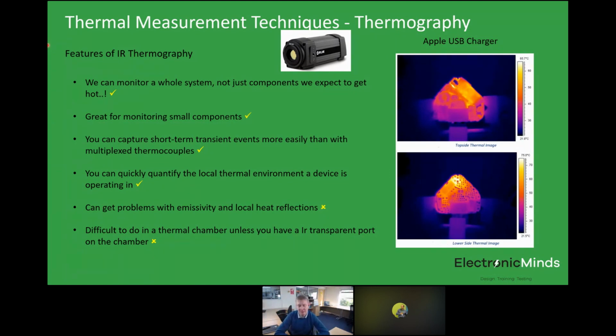On our earlier webinars talking about magnetics design, we talked about fringing effects. If you look at a standard E-core transformer and you put a gap just in the center leg, you get fringing fields going around that gap, and they can start to impinge on the first layer of primary winding and cause loss in that layer. There was a rule of thumb that I don't know how accurate it is, but it's been told to me a few times over the years: if you can keep your metalwork or your winding a distance of about 3 times the air gap away from the air gap. So if you have a 1 millimeter air gap, you need to keep any metal or winding about 3 millimeters away from it. You should be okay. Now, I don't know whether it would have the same effect for metalwork around transformers as well, but that would be a good starting point.